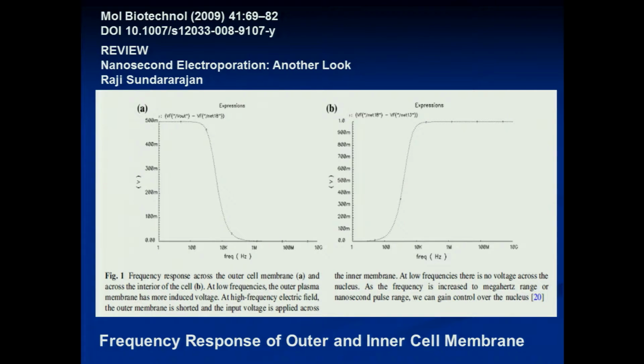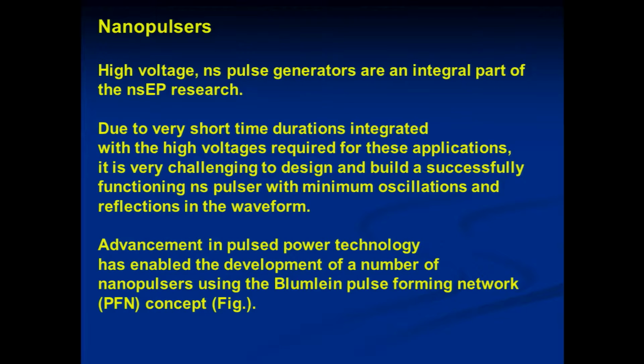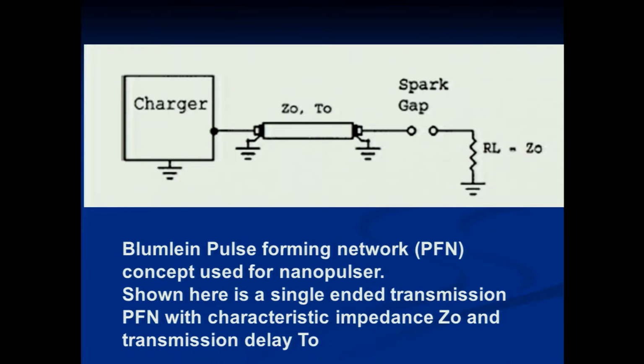We did some electrical modeling of the cells. Remember, at high frequencies the membrane is a short, so the current will go into the interior. At low frequencies, the membrane offers impedance. This is how we validated our model. Using our model, we could draw this curve, showing that at low frequency the membrane comes into play, and at high frequency the cytosol, the inside of the cell, comes into play. So we did all that, and then we studied a lot of other concepts.